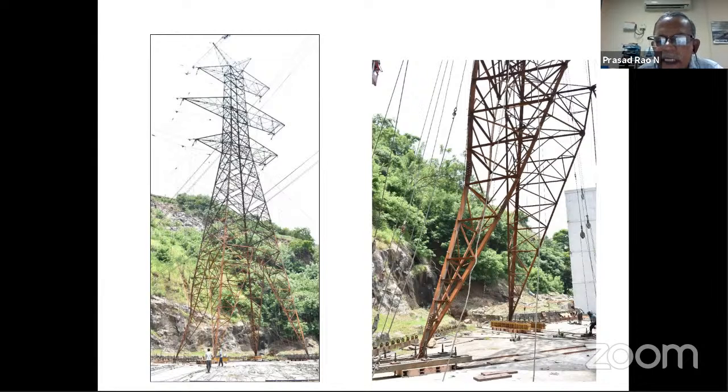Now the third time they are trying to address this by changing this main bracing member into a back-to-back member. We suggested reducing the extension and going for a two panel extension, that is, one 5 meter, 6 meter, another 6 meter, with K bracings. They don't want to change the design because the work on the foundation and other things has already been done. The capacity is failing because of instability in the structure, because of this very, very long slender column.